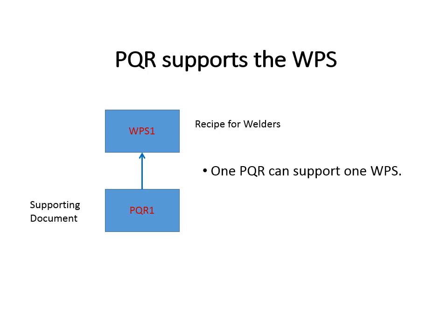They don't need to know, the welder should never ever look at a PQR. They should only look at a WPS. So a PQR is the document we have back in our filing system, and we show it to the inspectors or whoever might want to look at it to see that our WPS is supported by a legitimate PQR. So a WPS is a recipe for the welders. The PQR is a document that supports the WPS.